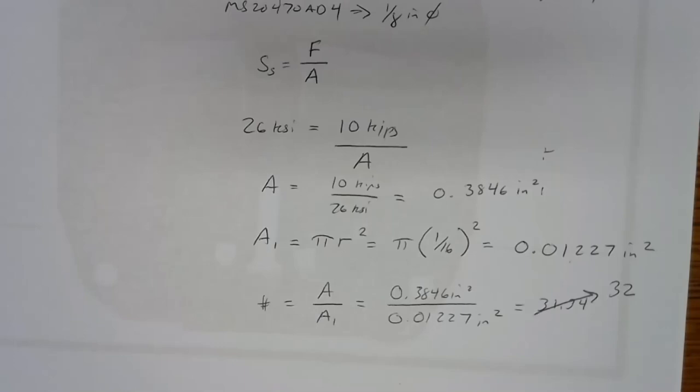Now, you've done this calculation in sheet metal, except you used a table. You went to the 4313 and figured out for each inch of width in my lap joint how many rivets I needed. Then you could calculate how many rivets to use, and you'd figure out your layout from there. Here we're looking at it from a strength point of view, and this is what we do without the 4313, relying just on the materials involved.